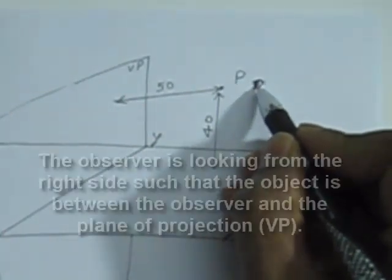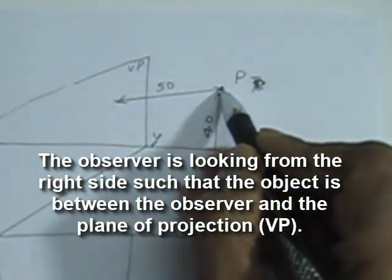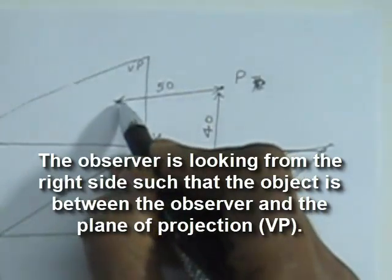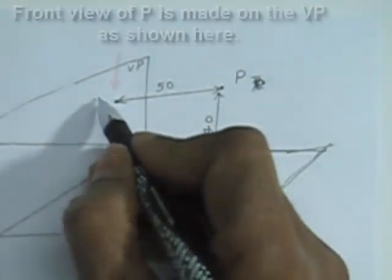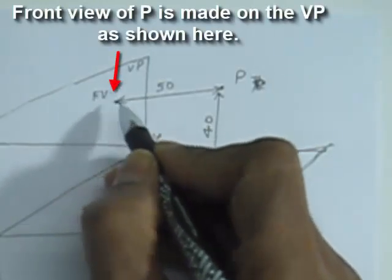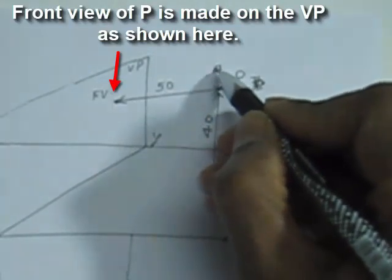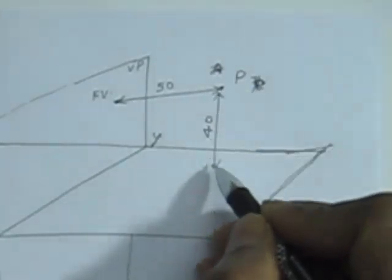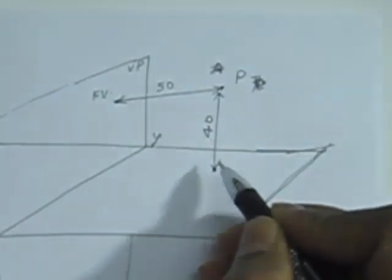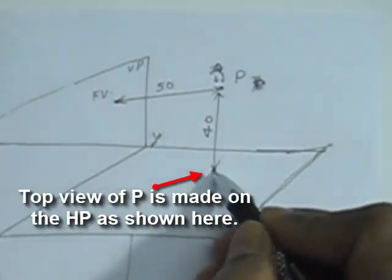Now the observer is looking from the right side to project point P on the vertical plane for front view. So the front view is projected on the vertical plane. For the top view, the observer is looking from the top such that the object is between the observer and the plane of projection.